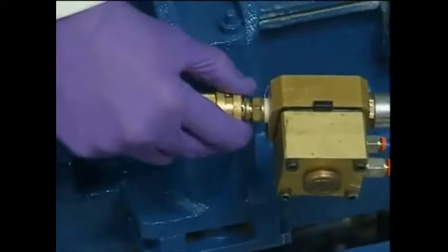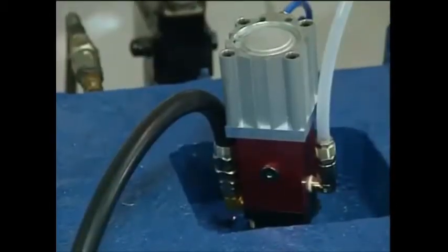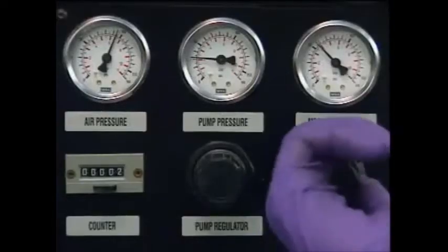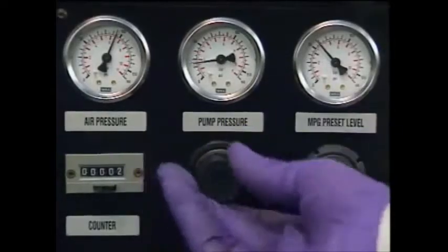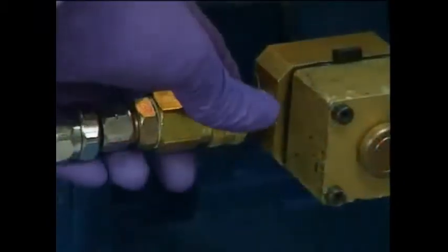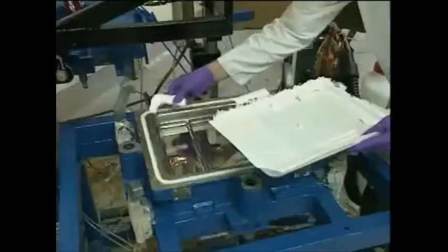Further automation can be achieved using auto-sprue technology. This valve is built into the mold and allows simple connection of the injection machine. At the end of injection, the auto-sprue automatically flushes the machine with solvent, and then the machine can be easily disconnected. Once the part has cured, then it can be demolded, leaving the mold ready for the next component.